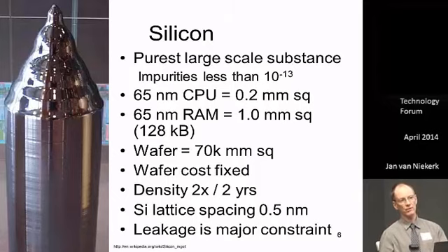So the latest technology says that we go from planar field effect transistors and we flip them on their side so that they stand up, and that is how Intel and the top manufacturers have reduced that leakage and allowed them to go from the 100 nanometers down to the 20 nanometer technology. So there's some technology where the leakage is minimum, and to us the leakage current is important because that's the standby current of our microcontroller.